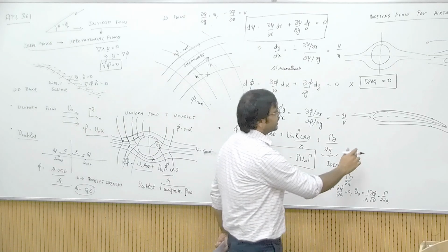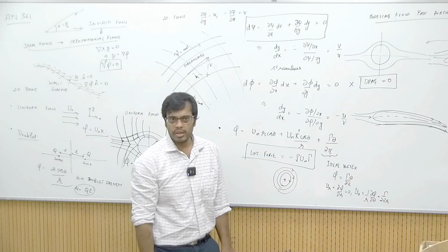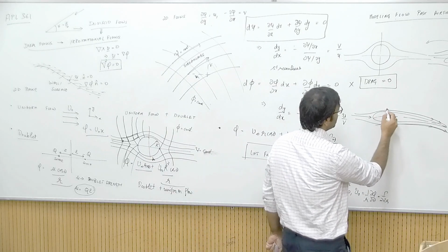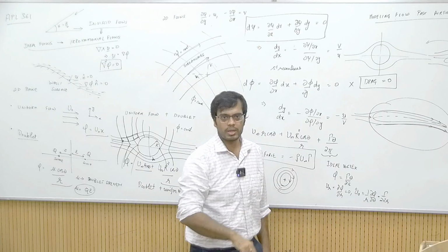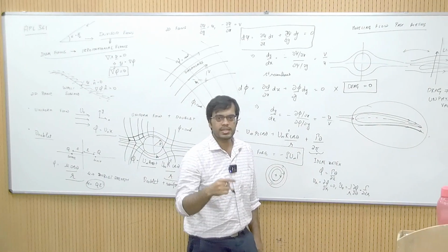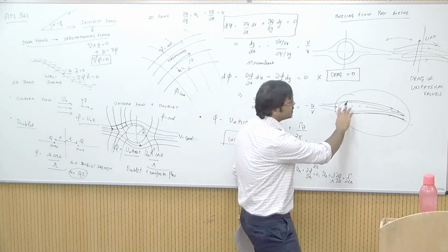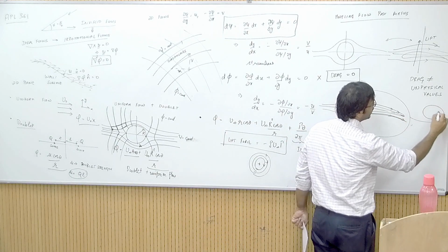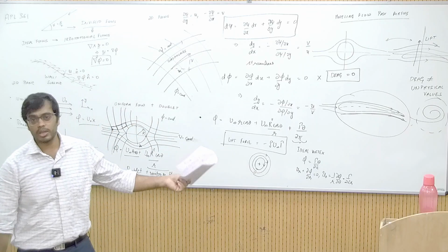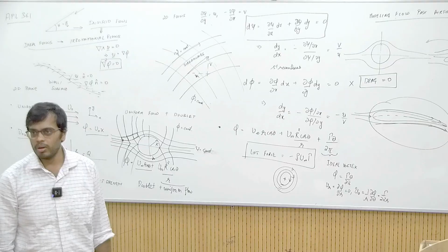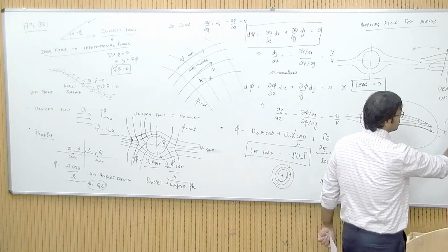The real reason why you have lift generated by an airfoil is actually that there is a net circulation. Okay, if you enclose a curve around an airfoil, you will see that there is a net circulation generated around the airfoil. Okay, and this circulation is actually completely opposite to the circulation generated in the trailing wake of the airfoil, because if you are considering everything to be an ideal flow, the net circulation has to be 0. Okay, so you do get some trailing vortex.